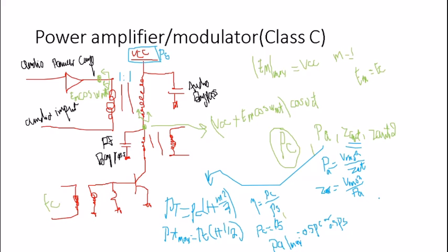Also, here we are only taking into consideration the maximum impedance for Z output. So again, here we are seeking the maximum impedance. For this to happen, the impedance needs to equal the conjugate of the output impedance of that audio amplifier. So Z output maximum, for it to be totally matched, needs to equal the conjugate of the output impedance of this amplifier.